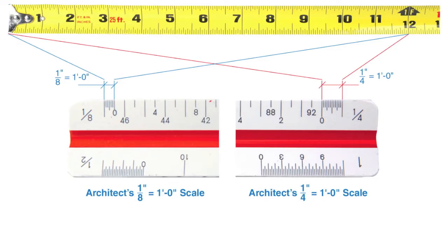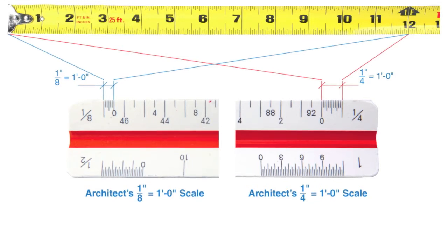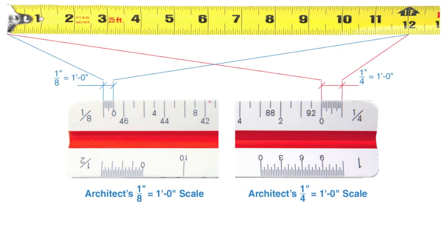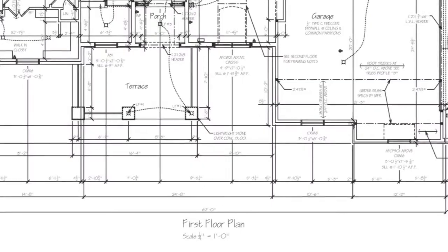This image is of two subdivided ends of an architect scale. To get important information on a construction print, an architect scale reduces the size of an object to a ratio equal to 1 foot in length. In this image, an actual quarter-inch distance represents 1 foot on some construction prints. You turn your architect scale to the desired ratio that matches the drawing scale you are reading.